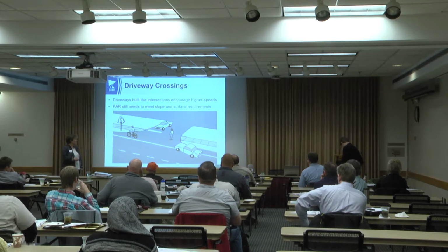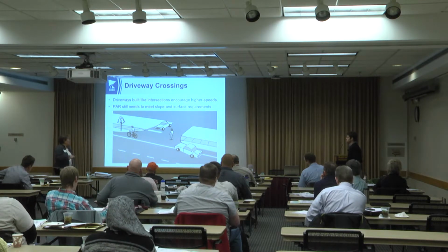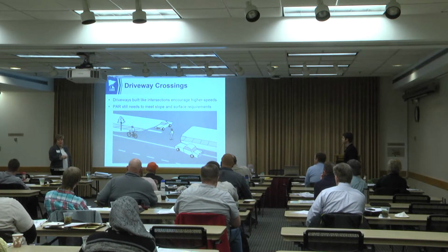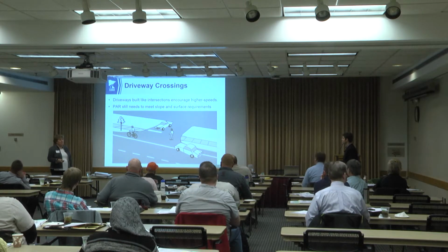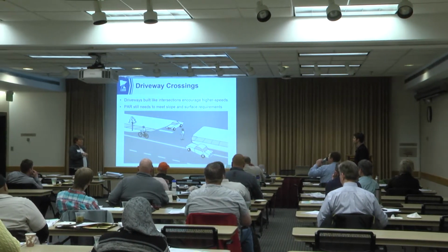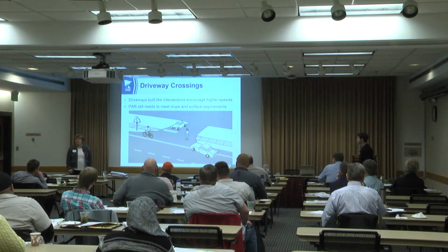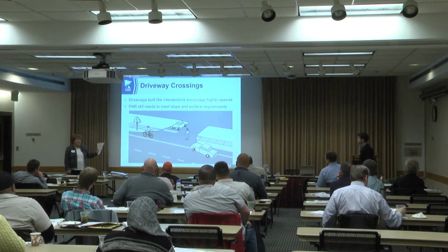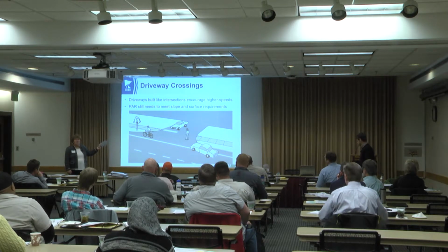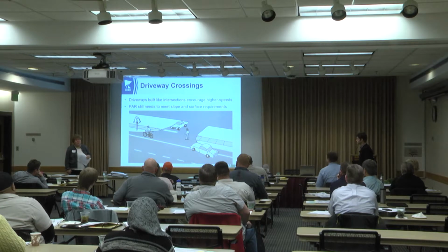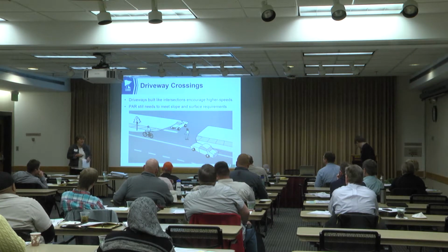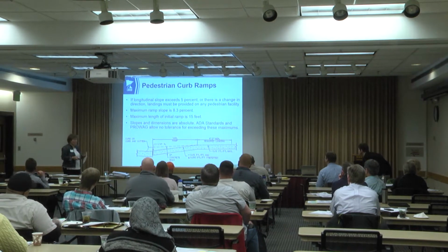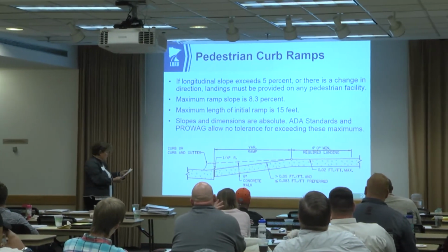Yeah, those of us that have worked with contractors or just worked with constructability know that here, unless you have a profile for this driveway or some other kind of added design feature, it is really hard to maintain that cross slope through there, right? I mean, the contractor's going to grade it. Even if you check it, it's hard to maintain a slope when they're going to pave this longitudinally. They're not going to pave through. So it's a really hard thing to maintain the cross slope requirement on something like this. Now that doesn't mean that these aren't all over the place. They are, right? It just means that when you do your transition plan, this would be something that you'd have to measure through, right? We did those at the university. So we know there's lots of stuff out there that is not necessarily 100% compliant.